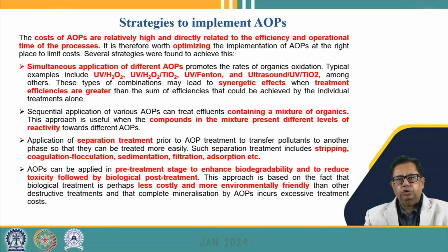This type of approach is very important in the sense that it becomes less costly and more environmentally friendly. If we apply the advanced oxidation process for the complete degradation or removal of the contaminants, the cost may become very high. But if we enhance the biodegradability of the water or wastewater that we want to treat, and then take it to conventional processes, like conventional biological processes, it becomes quite cost effective, which again reduces the cost.